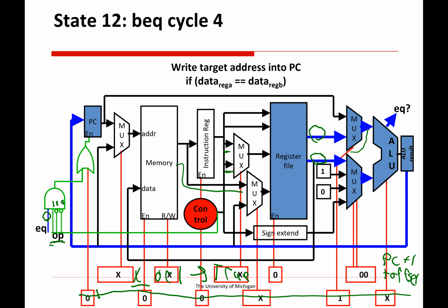And then these two muxes determine what's going into the ALU. We might be doing PC plus 1 or PC plus 1 plus offset. So that's why we have this result coming down. This is just if we're adding or ignoring register B with something. This is if that's register A. For this mux, we're choosing the second operand.